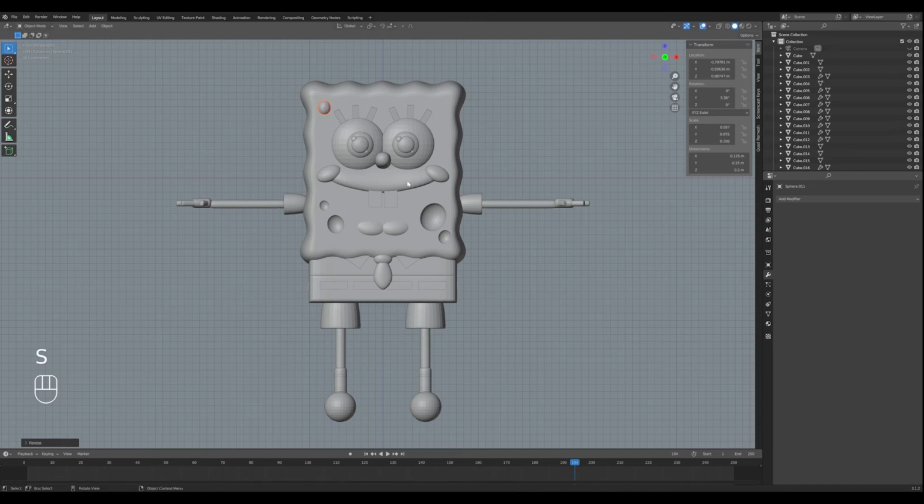Change the size. You know what? Let's go up a little. I'm just going to do one. Yeah, I'm going to do one hole right here. There's not much room right here by the eyelash. Okay, click the head, Boolean, fast, eyedropper, sphere, and apply.